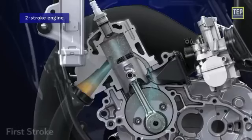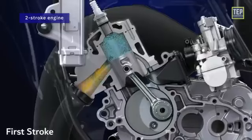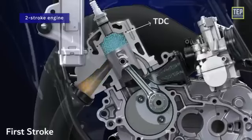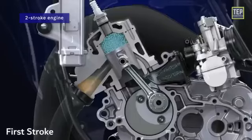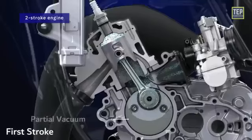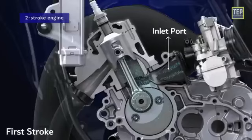In the first stroke, the piston is at its bottom dead center position. During this stroke, the piston moves upwards from bottom dead center to top dead center. It closes the transfer port and the exhaust port. The charged air and petrol mixture, which is already there in the cylinder, is compressed. Due to the upward movement of the piston, a partial vacuum is created in the crankcase and a fresh charge is drawn into the crankcase through the uncovered inlet port. At the end of this stroke, the piston reaches the top dead center position.